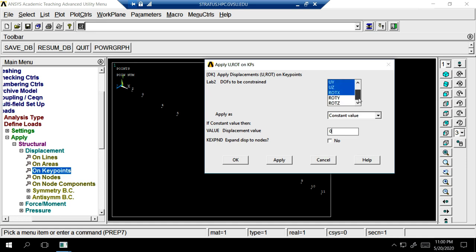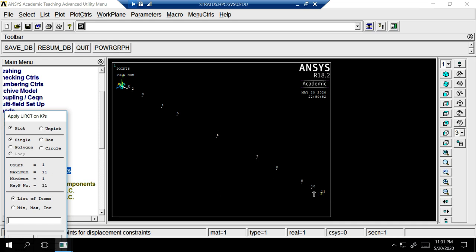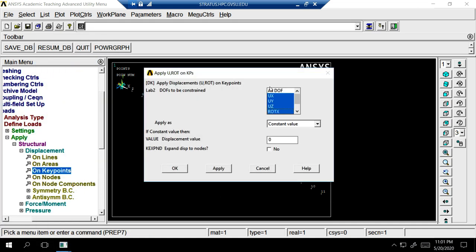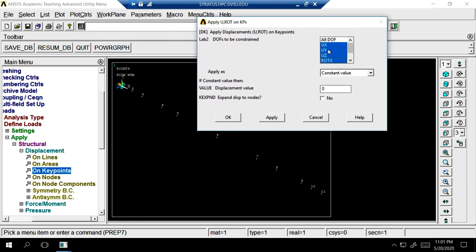Okay, so of all these, I have blocked them. On the right side, the bearing on the right side, let's see what we can do there. You know what, we can let UX be free too, let that slide, because on the other side of the shaft I have that fixed in X direction, so this shaft is not going to move in X direction.